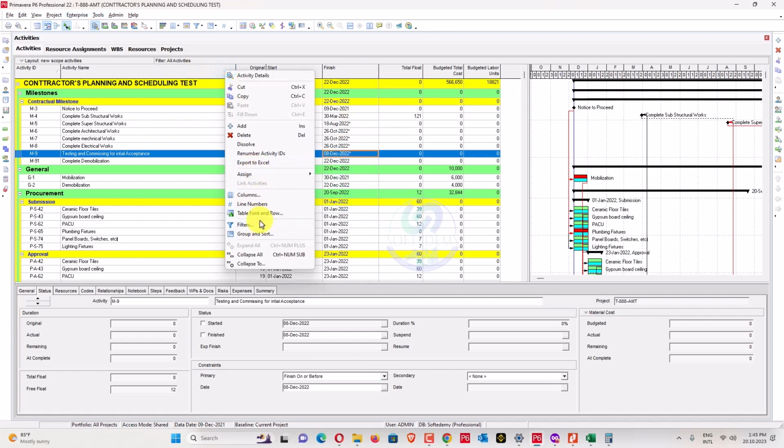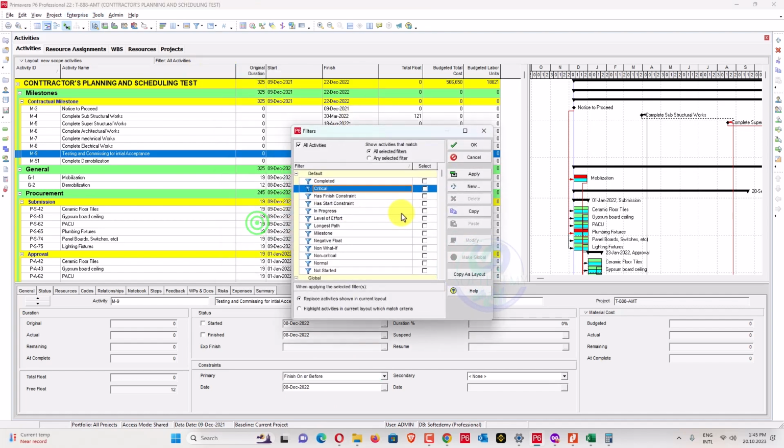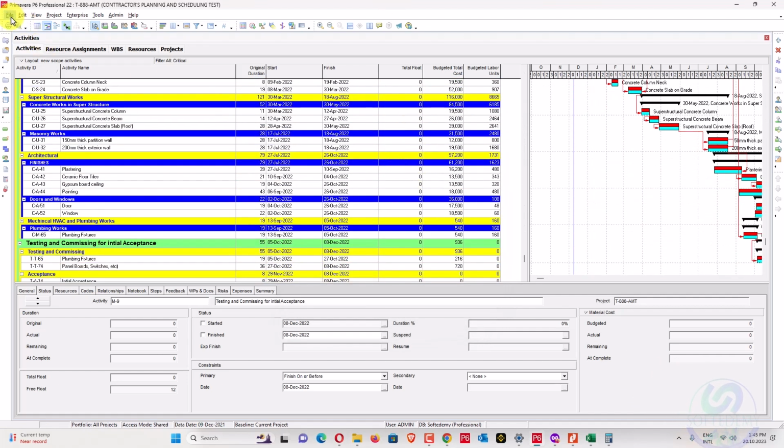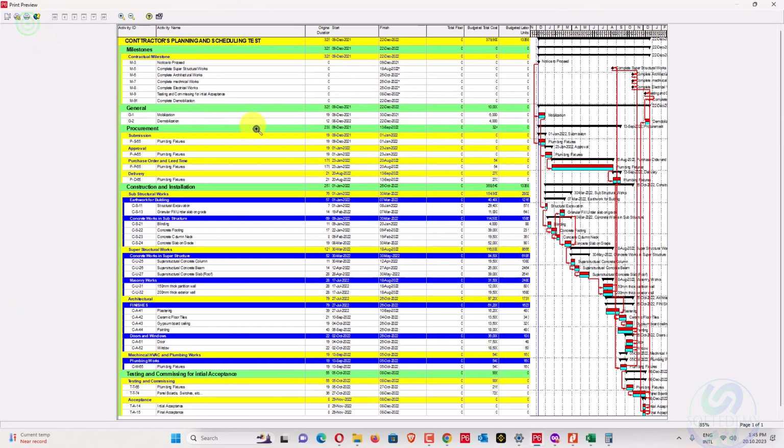because dates were changing. That's why I just go back, because the dates which we are freezing are changed now. So now we'll select critical. Okay, so we have a critical path which is very proper. And now we'll go here, print preview. You can see here that the critical path is much more proper. So this is one of the planning basics. This is the basic one.